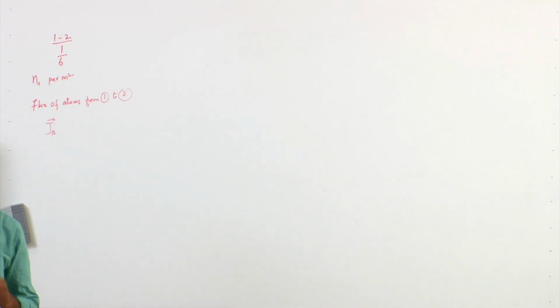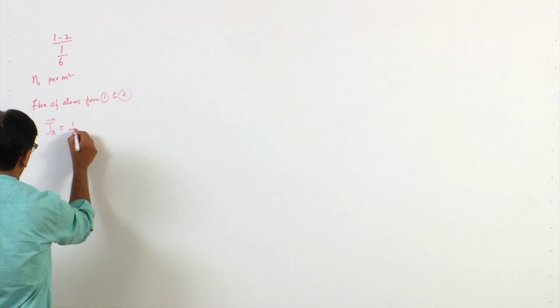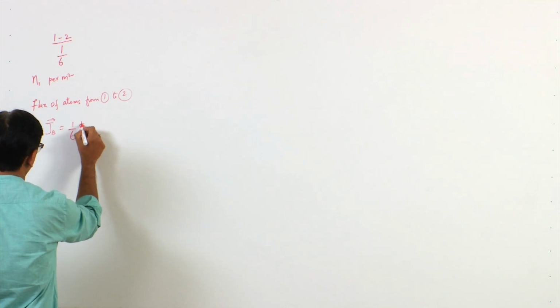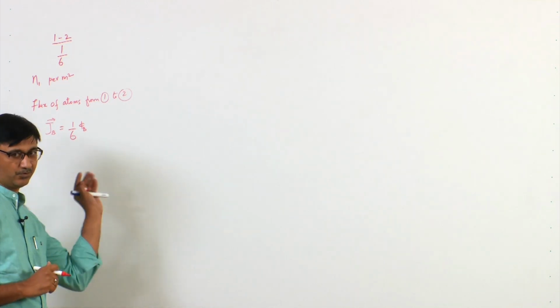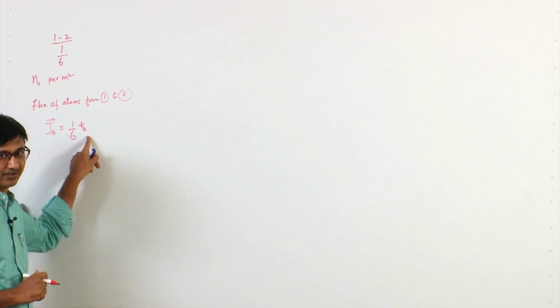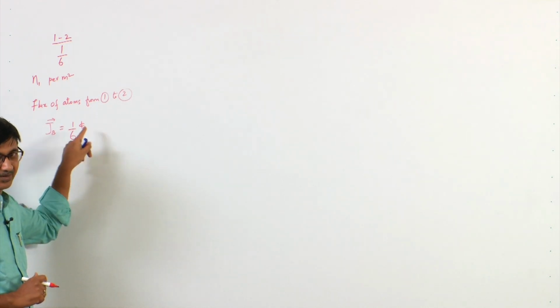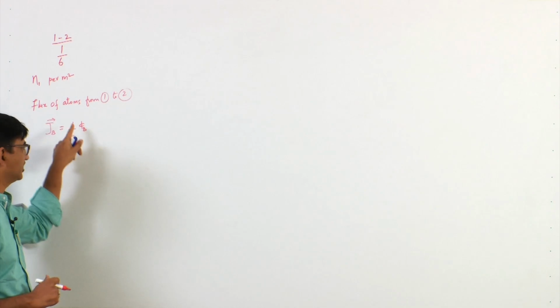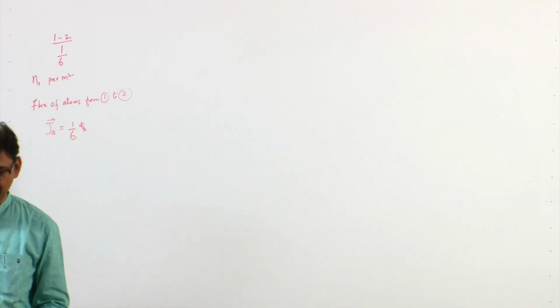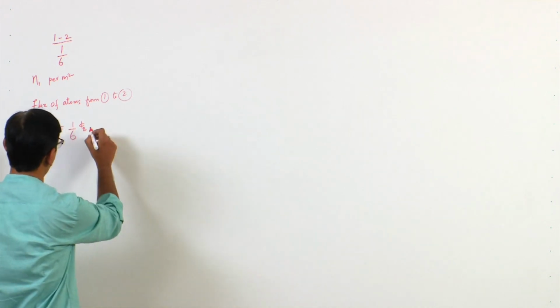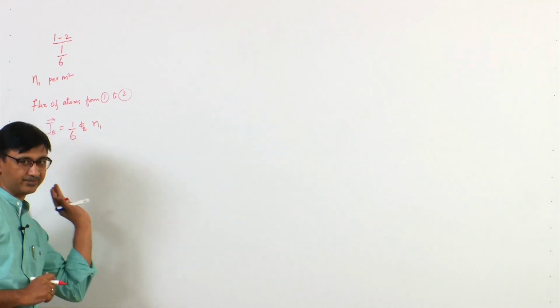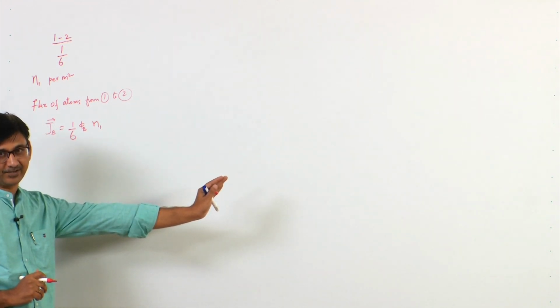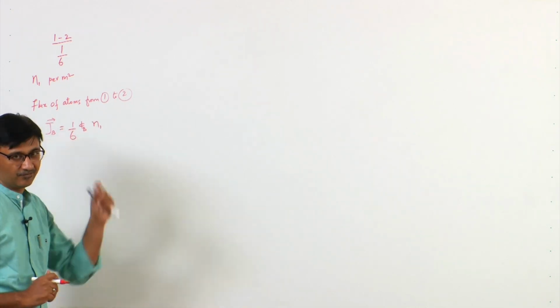JB equals 1/6, the probability in that direction, times phi b, the number of jumps per second an atom does. So from plane 1 to 2 it will be 1/6 of phi b, times the number of atoms we have in plane 1. That many atoms will jump from plane 1 to plane 2. This will be the flux.